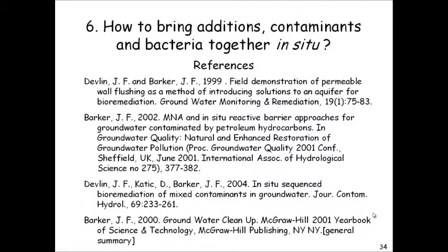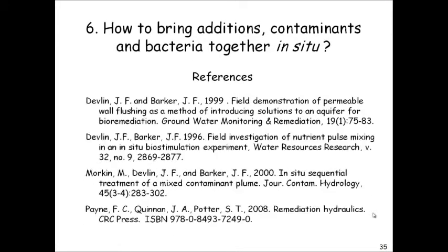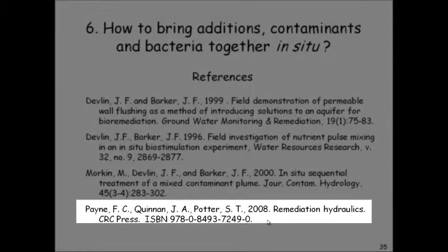Here are a number of references to this section on moving things around in the subsurface. Again, I'll point out this last one, the textbook by Payne et al., where they really do, I think, get remedial hydraulics right on. So how do we bring contaminants and bacteria together in situ? The commonest way is to add water that contains whatever we need, electron acceptors, nutrients, things like that.